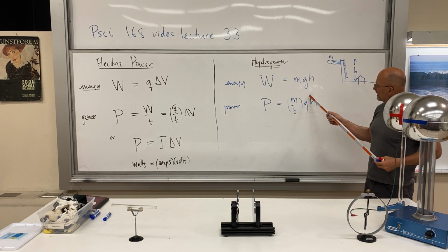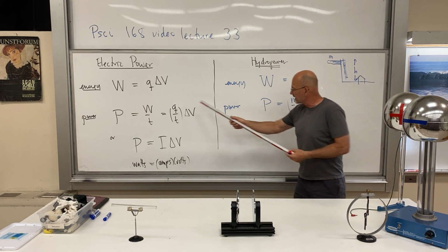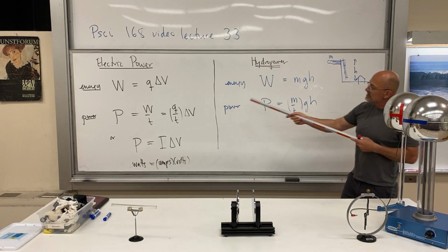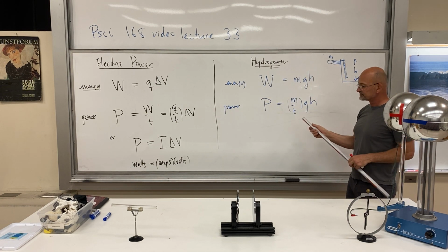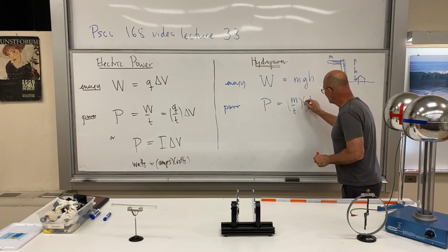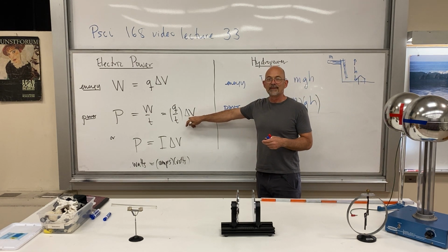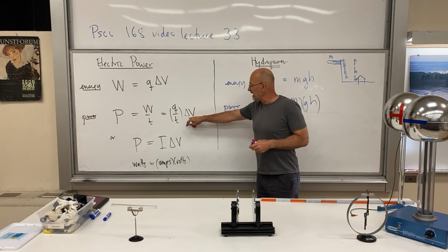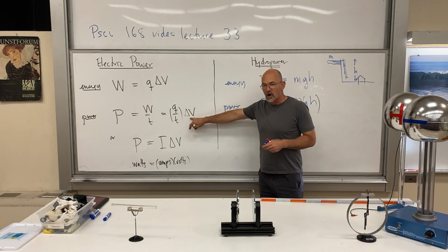But you've got a flow rate here, you've got a flow rate there, right? The current, the flow rate in water. This, of course, is joules per second. This is kilograms per second. But because of this analogy, we can see that G times H plays the role of a voltage. It's called a potential. And we even call this the potential drop.